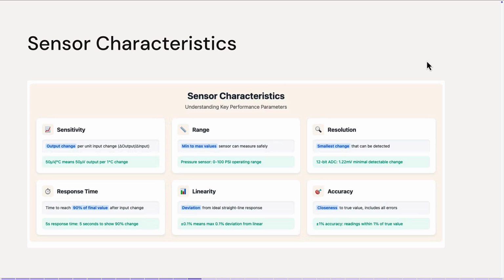For example, this is a temperature sensor. When you buy it, maybe you have refrigerators or freezers working at -50 or -60. It's possible that this sensor doesn't work. It has only a limited range. Maybe it can measure between, I don't know, 5 degrees and 35 degrees, and above this, it will not have any kind of response. This is what we call the range.